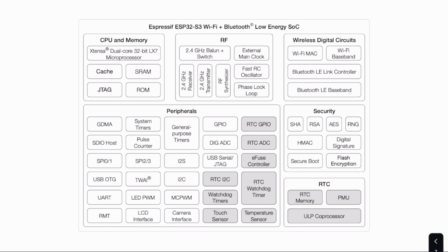On the chip, you'll find a USB communication device. You'll find UART, so that's universal serial interface. You'll also see mention of PWM and I2C. Those are communication interfaces that we'll be using for, in the case of PWM, the motor driver, and in case of I2C, many of the peripherals that we'll be using. Peripherals is essentially the name of anything that's not part of the main chip's functionality. It's not part of sort of this core part here. We'll also be using GPIO and the Wi-Fi modules that are built into the chip.